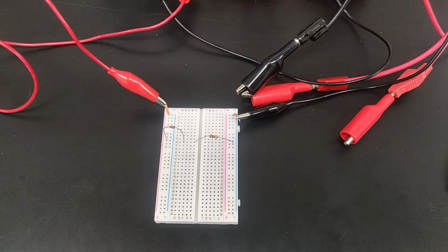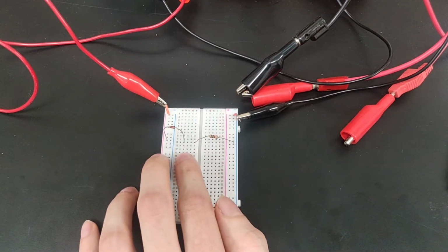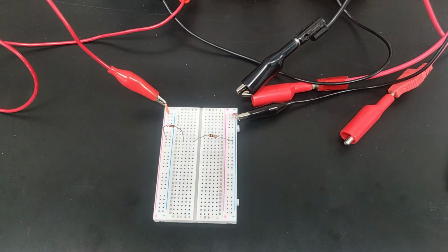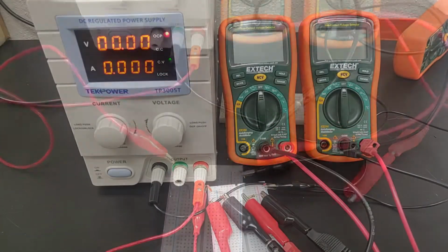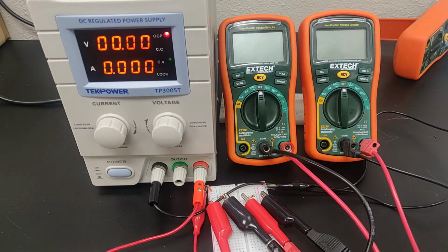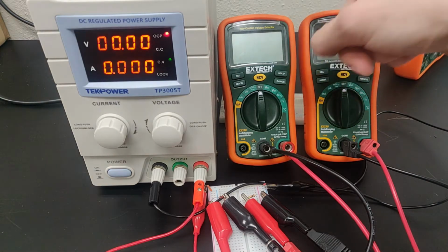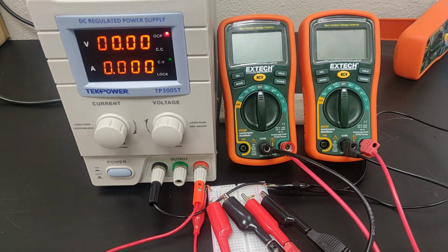So before we actually start making our measurements, one thing that I would recommend is that you open up an Excel spreadsheet like you hopefully did for the previous video, so that you can very easily populate a column with the voltage across the diode, the voltage across the resistor, and then calculate the current, and then we can make a nice plot. But with that, let's start by measuring the resistance for our 1000 ohm resistor. So this is going to be my setup for the measurements. The multimeter on the left is going to be measuring the voltage across the diode, and the one on the right is going to be measuring the voltage across the resistor.